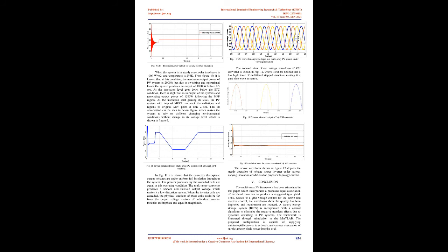4. Simulation results. Detailed simulation studies are carried out on the MATLAB/Simulink platform, and the results obtained for various operating conditions are presented in this section. The values of parameters used in the model for simulation are listed in Table I. The steady-state response of the system during the MPPT mode of operation is shown in Fig 8 during slow change in input to the system, varying solar radiation input to the PV system. The system response for ramp changes in the source insolation level while operating in the MPPT mode in conjunction with the DC/DC boost converter is shown in Fig 9.